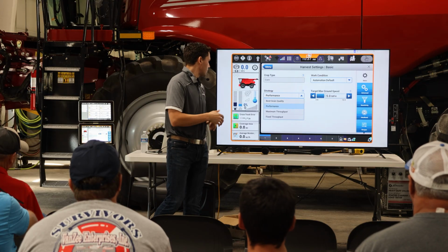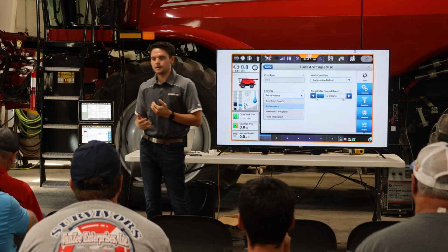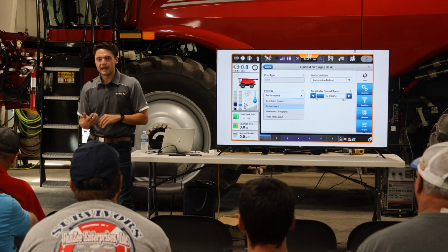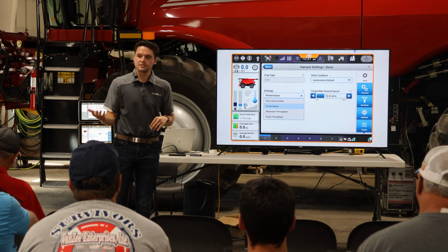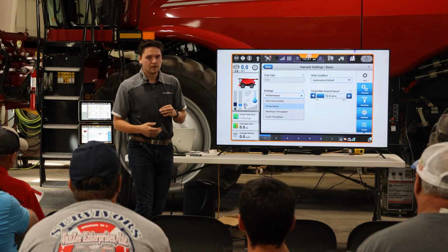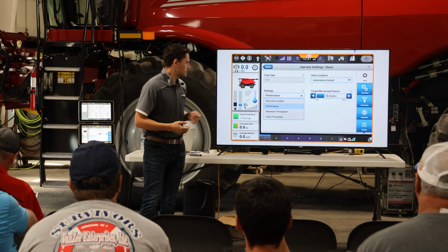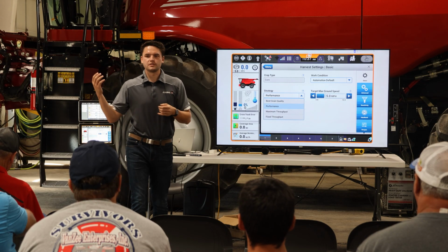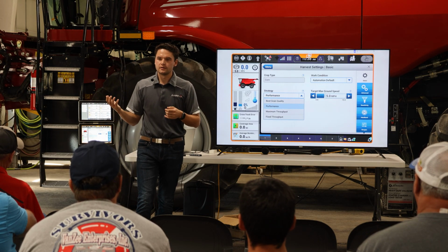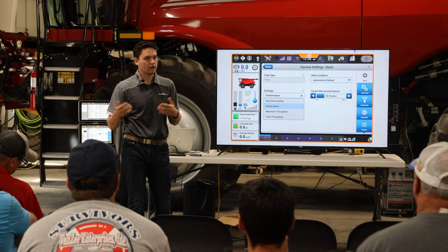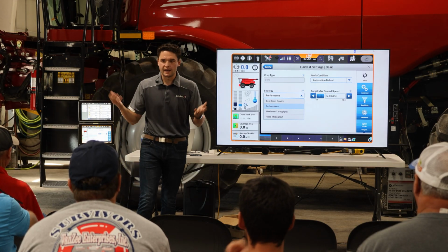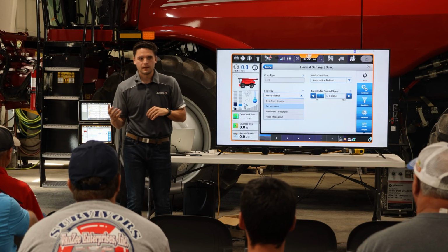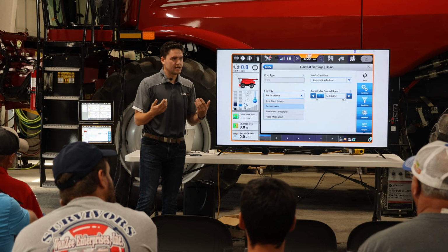But moving back to our best grain quality, let's look at some operational experiences we might have with it and things that it might prioritize in certain areas versus others. So let's say we're going along and we have the best grain quality selected, and our machine starts to see MOG. Okay, MOG, if you're not familiar, material other than grain, is getting high. So it's sensing it, it knows that I have a MOG issue. So it decides to address that and fix the MOG.